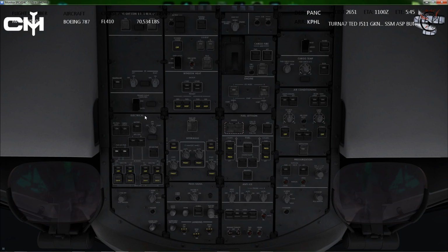Basically what you're doing at this point is you want to get to a point where you pretty much remember how things are going to go. So for example, I can basically go down here. I know these lights are all supposed to be on. APU should be off and default light should be out. That doesn't do anything. Well, it does something. It pops that up. External power we're using right now, I know all of these should be on with the off lights showing, and the drive lights should all be showing as well, and the wiper should be off.